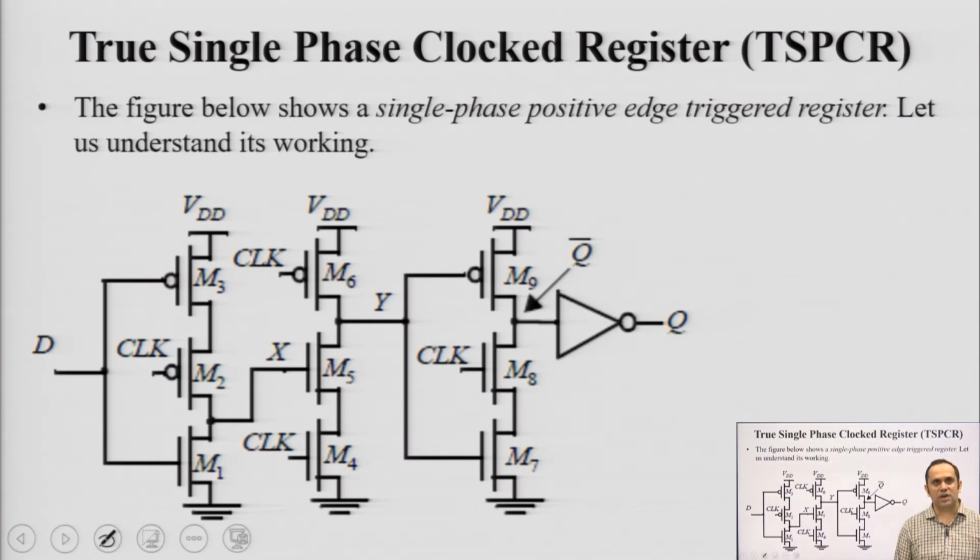So, what we are doing? We are trying to understand dynamic sequential CMOS circuits. And in this we have come our way to a circuit where only a single clock is being used. Even though we are using NMOS and PMOS, we are not using clock bar, we are only using clock. So, suppose when clock is 0 initially, M2 is on, right.